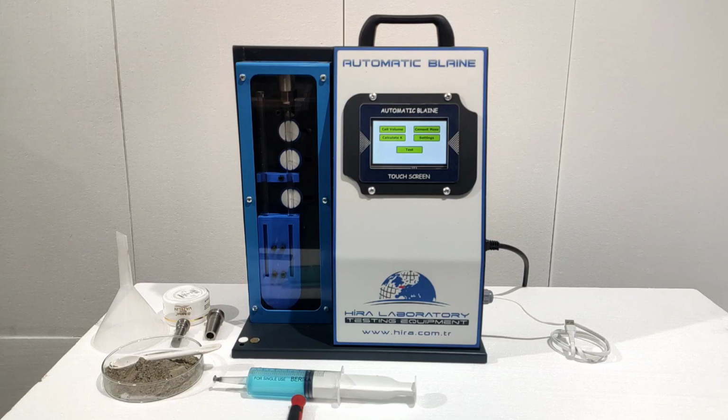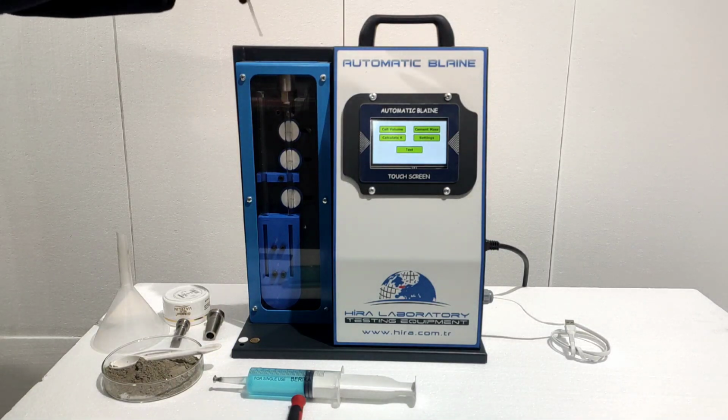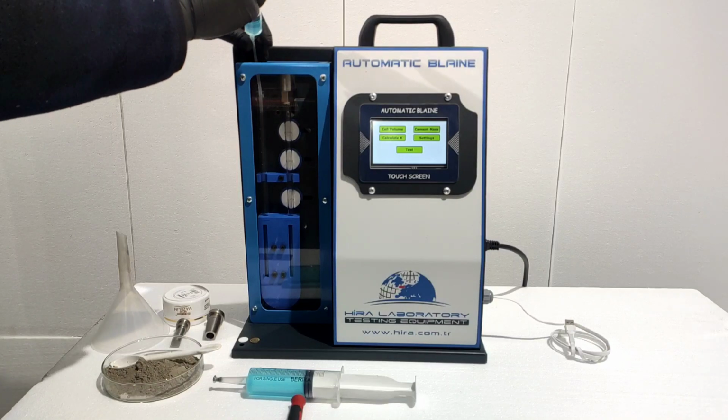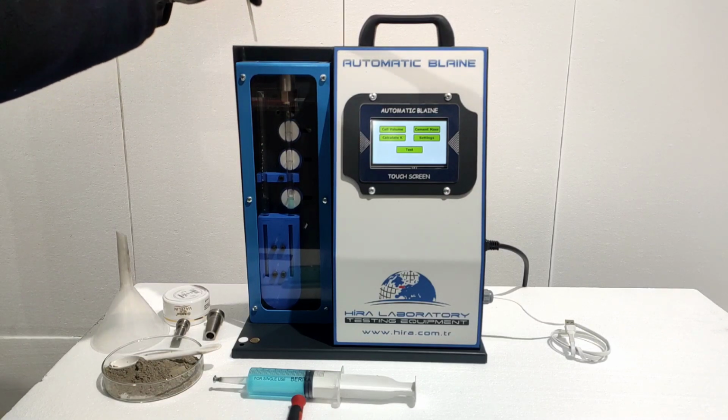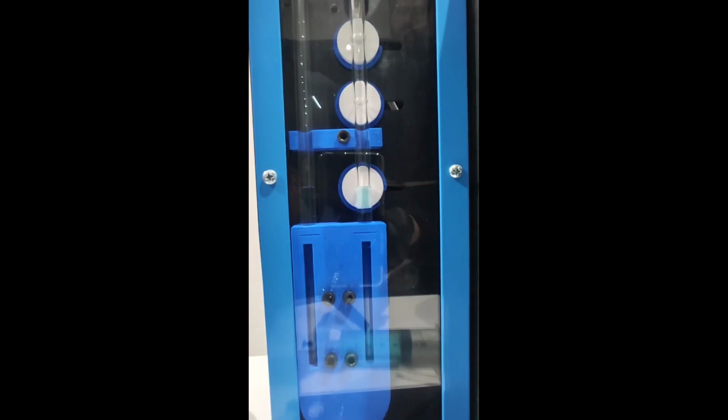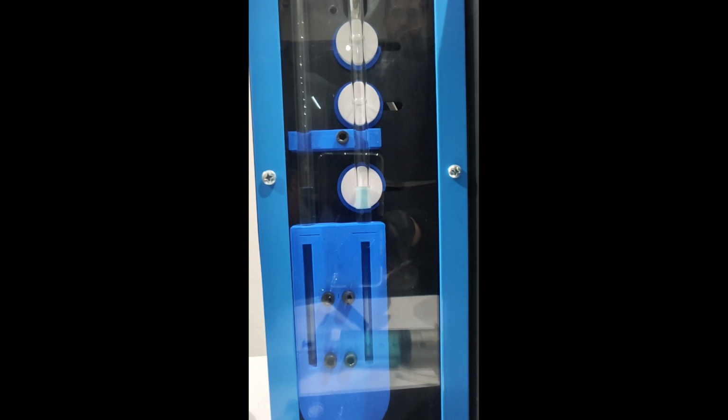The manometer fluid should be put in with the help of the filling syringe. Insert the syringe tube into the U manometer tube and fill up to the bottom line. The U tube must be clean and dry before filling. Since the indicator is set very slowly, the liquid must be filled gradually. If the fill level is exceeded, the excess pressure gauge fluid should be carefully drained using the syringe.